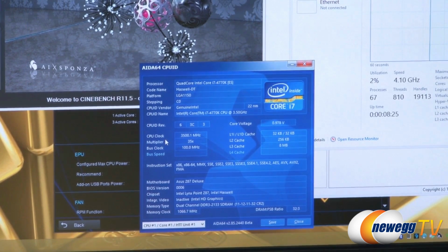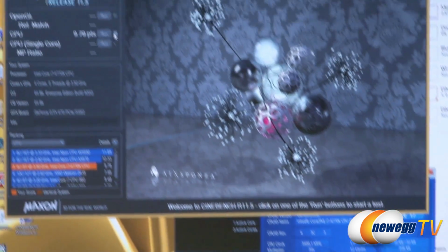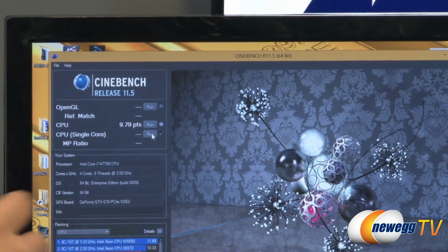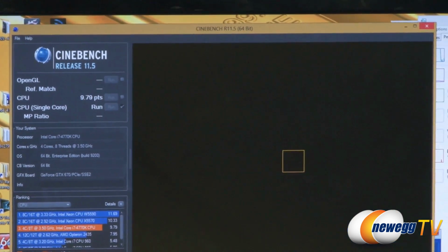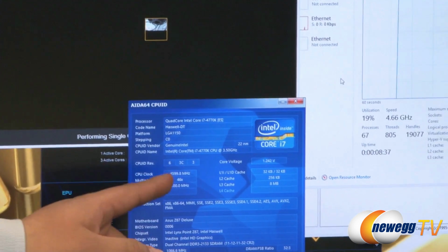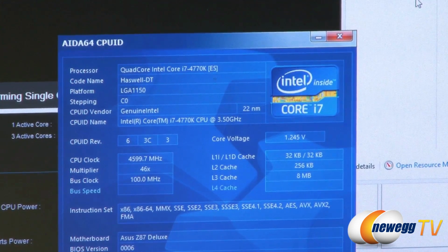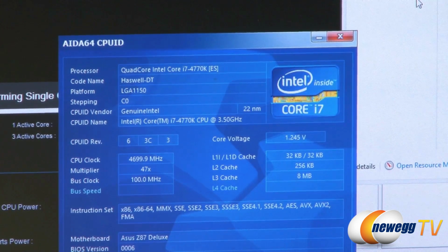And if we go ahead and run single thread, the Intel Turbo technology, based on temperatures and other factors, is going to go ahead and also allow us to take advantage of that per core tuning that we went ahead and set on 4.7 gigahertz. So you can see right there it already had started at 4.7, and it'll go kind of up and down depending on, like I said, the thermal characteristics of what's reported by the sensors inside the package.